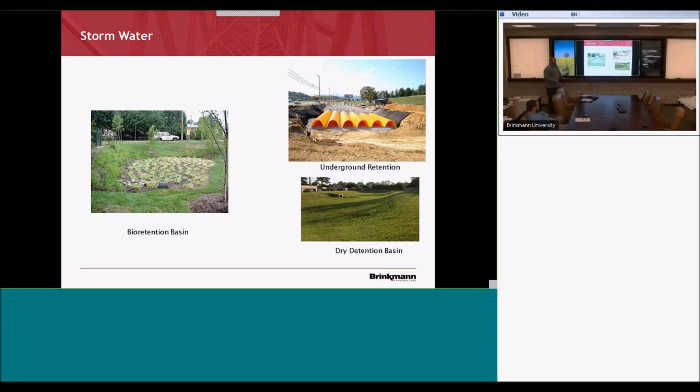The main thing is you just need to talk to your owner and make sure he realizes what he's getting. It's a maintenance nightmare. You can't plow it. It fills up with dirt. You've got to vacuum it out over time. And there are all these agreements with the MSD that you're going to maintain it. So you just need to have those expectations so he doesn't show up one day and see it.